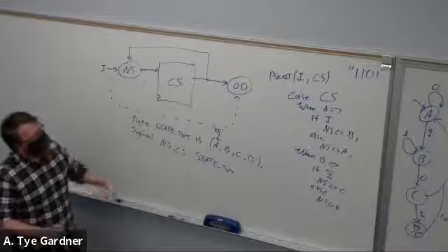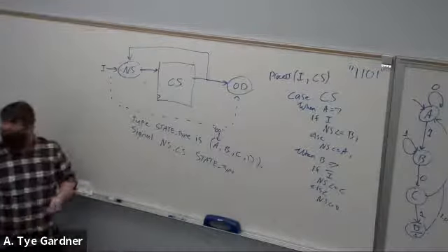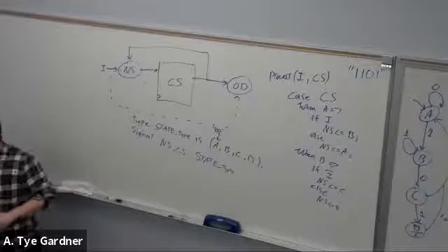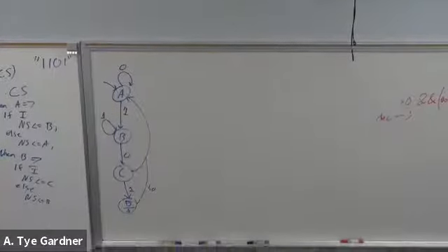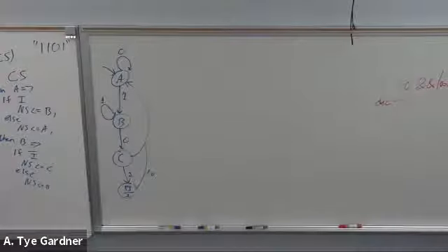All right, I'm not going to finish it. That's our next state decoder. Now, well, current state is just a register. It's not doing any real thinking, but we need to update that register, right? Because what's happening is each time I see a rising edge of a clock, I'm taking whatever the output of this next state is, this NS, and I'm loading it into current state so that it can be fed back around.